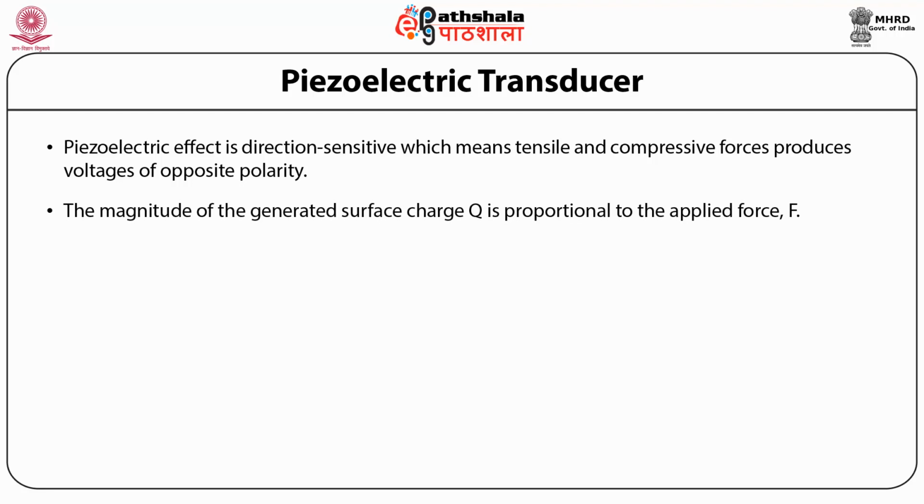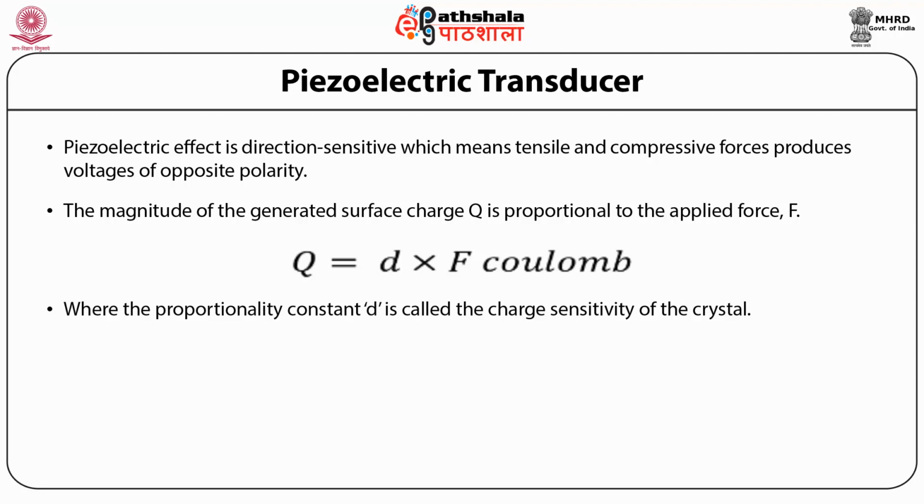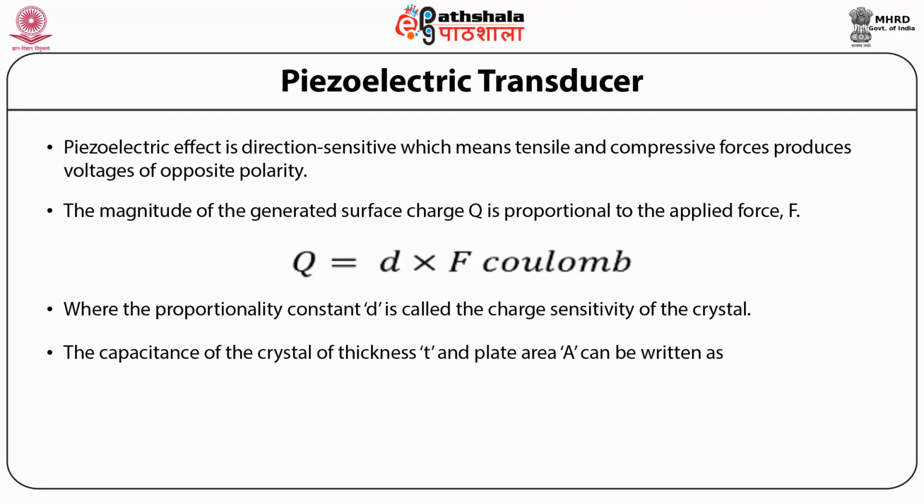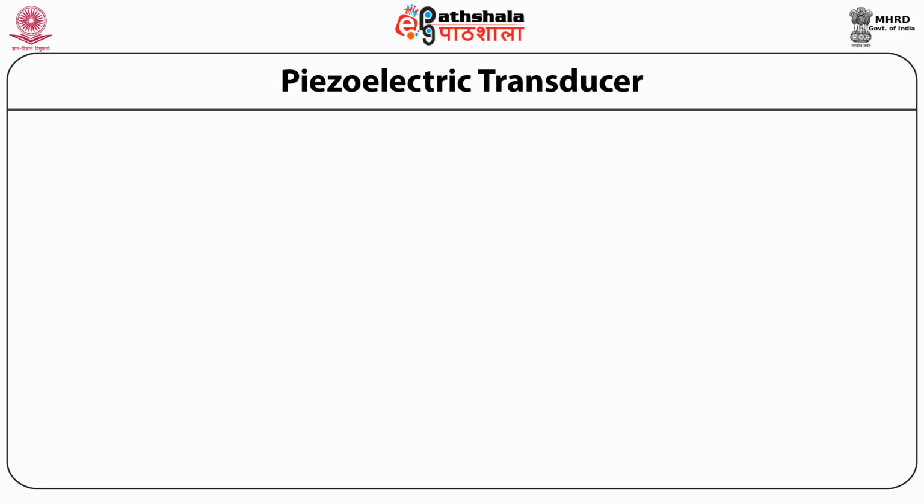The magnitude of the generated surface charge Q is proportional to the applied force F. That is, Q = D × F coulomb, where the proportionality constant D is called the charge sensitivity of the crystal. The capacitance of the crystal of thickness T and plate area A can be written as C = ε_r ε_0 A / T.